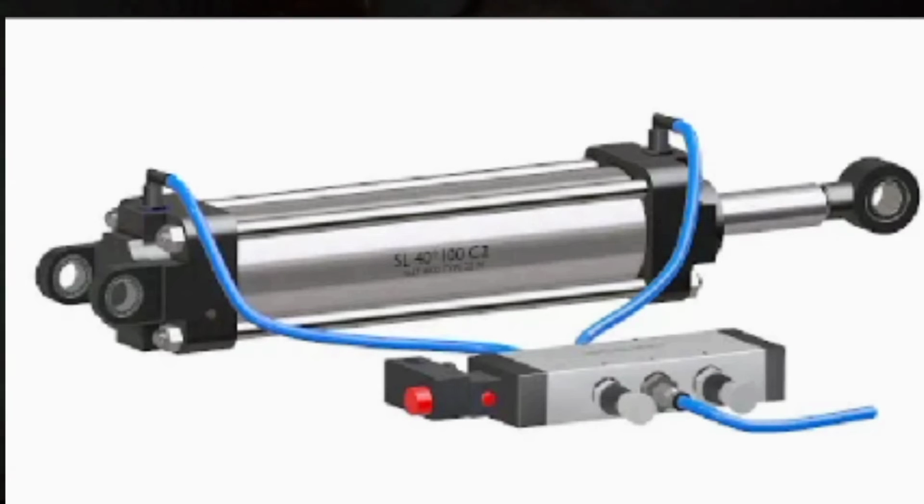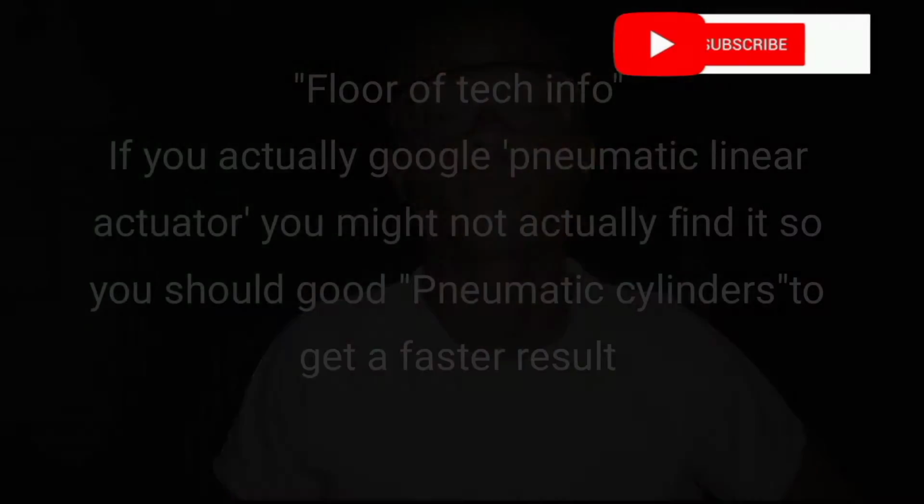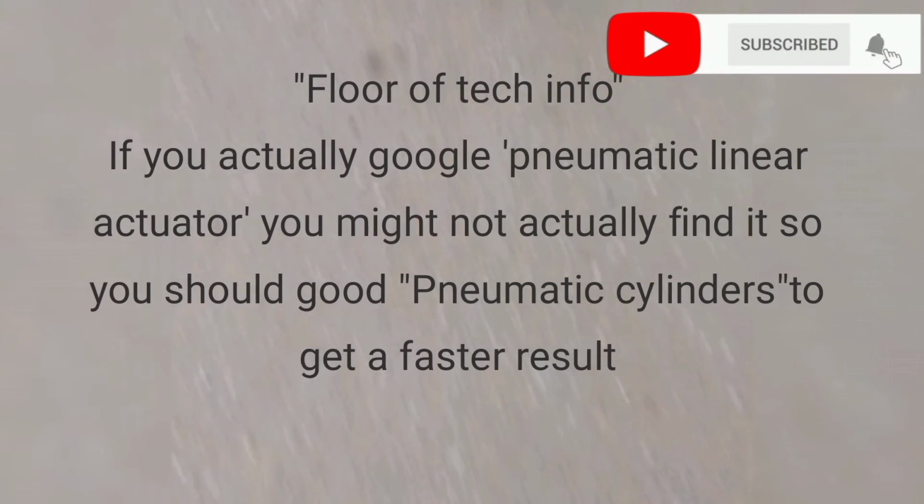If you watch The Hacksmith video, I know from Jim Upswing, when they made the exoskeleton, you can see he used the pneumatic actuator, which was able to move the exoskeleton up and down. So a pneumatic linear actuator is just an actuator that uses compressed air to produce high force.